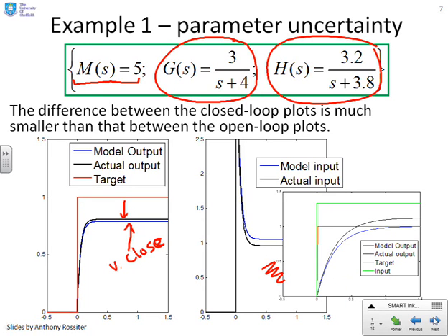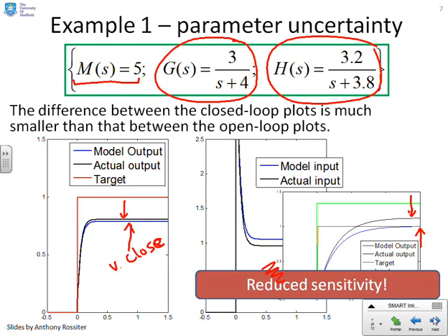Here we've put up the open loop responses that you saw in video 1. So what you might want to look at is what gap we had between the responses when they were open loop, and you can see it was quite a big gap. Now that we've closed the loop, the gap between the two responses is very small. So this feedback has dealt with the uncertainty far more effectively, and that's because of the monitoring and the correction. In summary, we've reduced the sensitivity to the uncertainty by introducing feedback.